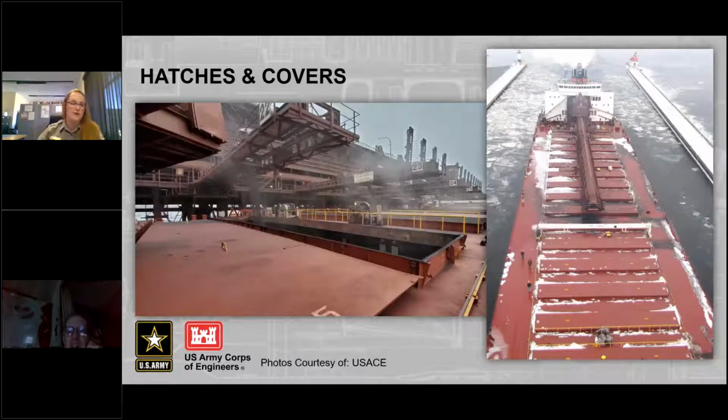Today, on modern vessels, we have huge steel hatch covers, like on the James R. Barker. The Barker has 36 hatches on her deck, which open into 7 cargo holds located below deck. And each hatch covering measures 65 by 11 feet, and they weigh roughly 6 tons each. So you might be wondering how they get them off. Mounted above deck is a crane, and that crane will do all the heavy lifting of those hatches.